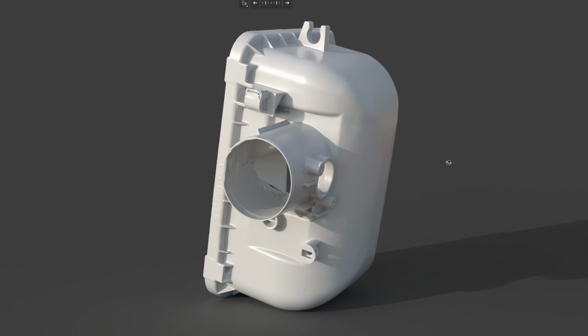When the original part that you are going to reproduce is made from plastic, it's likely that you can 3D print that part and get the same functionality, because the 3D printed filament has similar properties to most automotive plastic parts in both strength and stiffness. So when I reverse engineer this part, I'm going to maintain the stiffeners that the original designer provided.